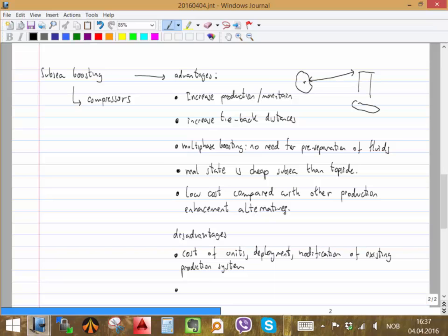Remember that the pump has to be controlled, so you need a control module. There also have to be some safety barriers. It also needs electrical power. You also need to measure, so it needs instrumentation. So you can't think that it's just a simple pump and that's all. It has a lot of things around it, and sometimes the space or the requirements of all those other things are more costly than the equipment itself.